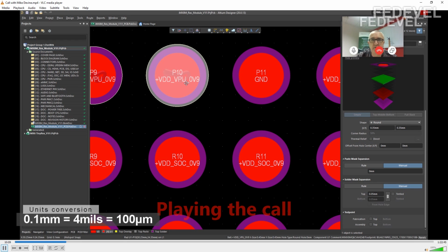I mean, a rule of thumb really is that you want to have the aspect ratio of 0.75 to 1. So if, let's just say, you had a thinner dielectric, because you have to take into consideration the thickness of the pre-pregs that are available. Very common is a single ply of 1080 pre-preg, which is roughly about 75 microns thick.